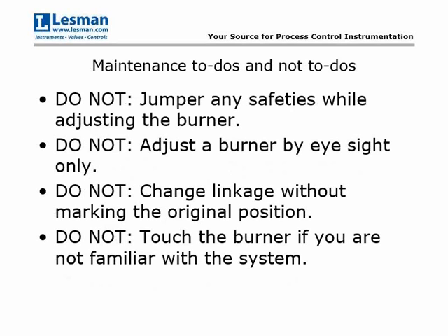High and low gas pressure switches: I know that as you're adjusting the burner or maybe tuning the burner for the first time, you don't know where those should be set, but you want to put those in place and not jumper around them because, of course, you're going to be physically lighting off the burner, and even though it's not production and it's going to be supervised, you're not always going to be able to detect right away if you have a regulator failure and a high gas pressure switch alarm.